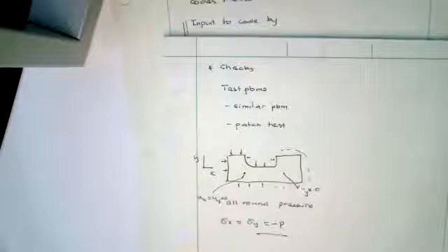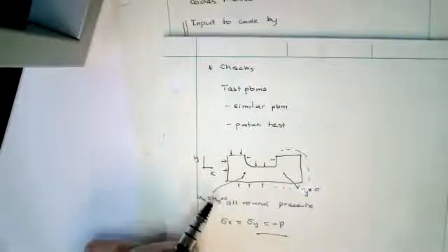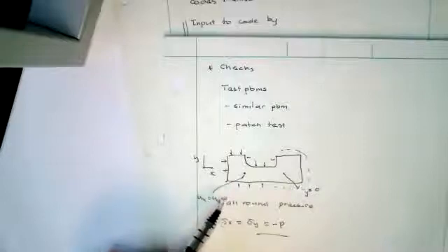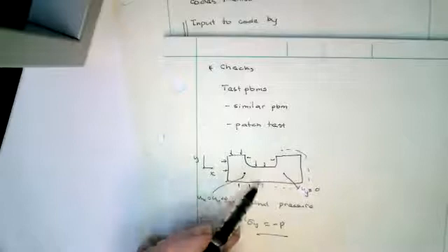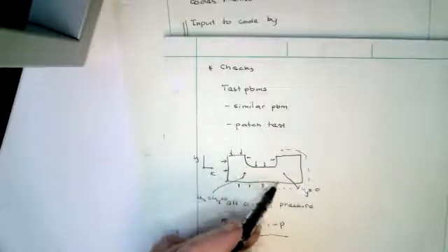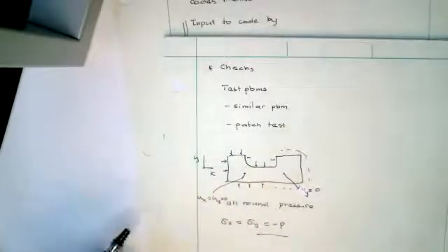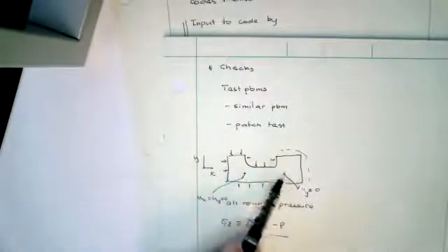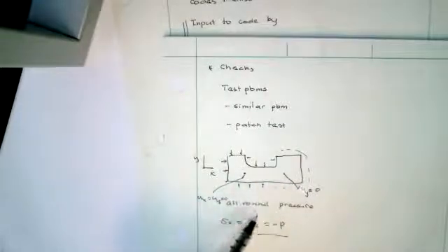So one of the things you can do, and this is a very easy boundary condition to put in any of these codes, is constant pressure. And so you can run it and make sure your mesh is properly connected. If you generated a mesh here and you've connected it to some other mesh and you've got a gap, you won't get constant stress, okay? So in simple problems, this is a very simple test. For more complicated problems with mixed meshes, this is a good test to do.